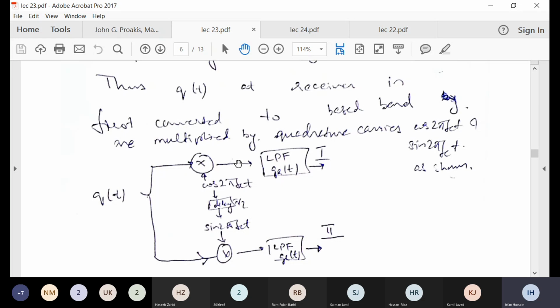The same is actually being used. This is a receiver. The same receiver that is used there can be used here, and actually this is the standard implementation in all of our wireless communications from 2G, 3G, 4G. So you are actually sending your signal exactly like that. The signals are coming, and then you are multiplying this with cos, and then you are multiplying this with sine. All right.